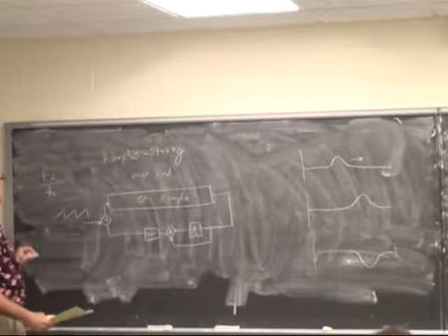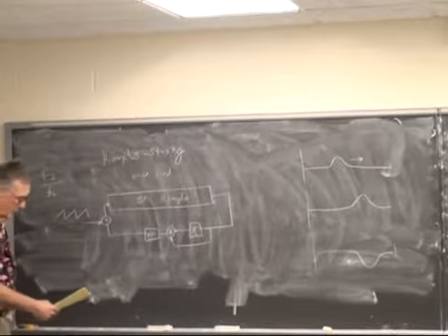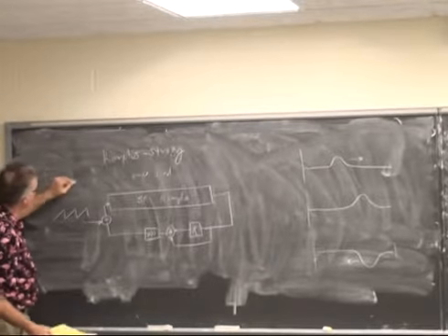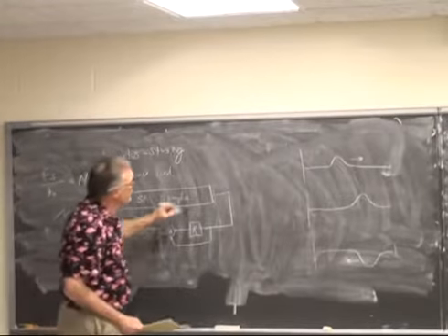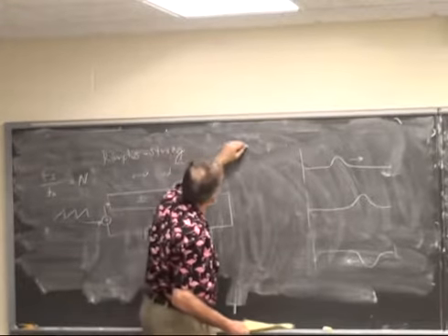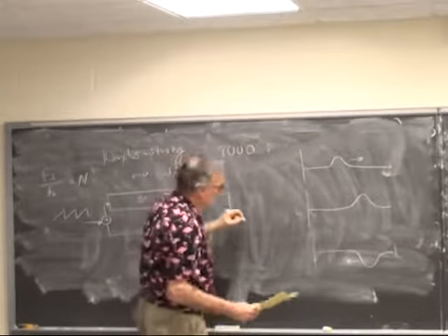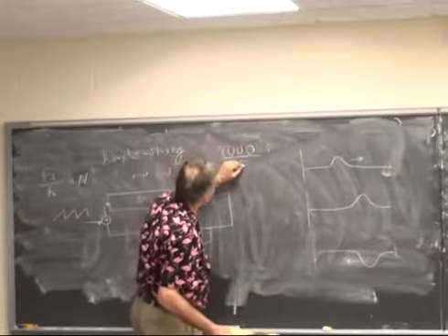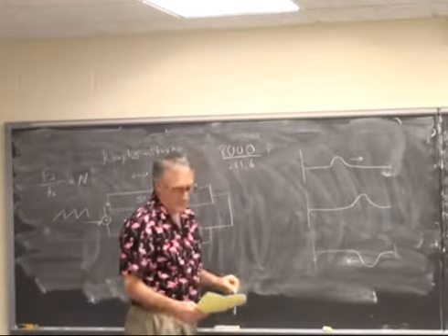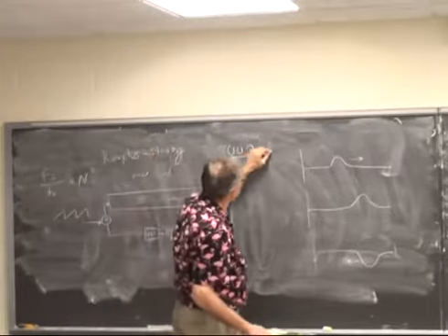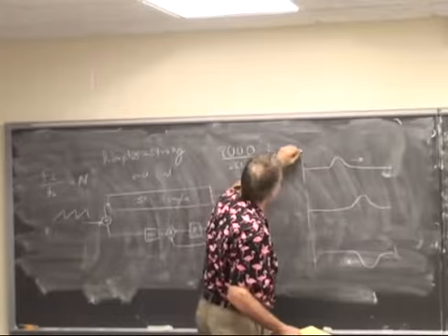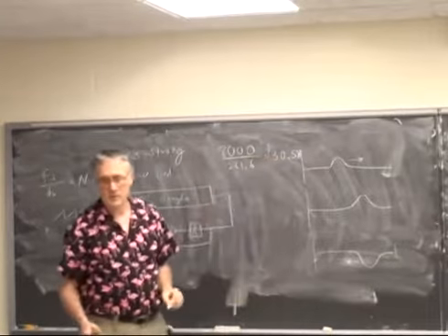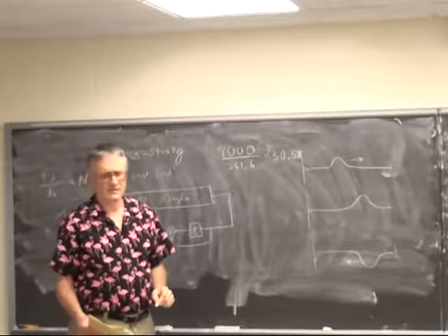Then that will give us the number of delay steps. If we were to choose 8,000 samples per second and 261.6 hertz, which is middle C, we would find that the length of the shift register has to be 30.58 steps. Oh, that stinks.